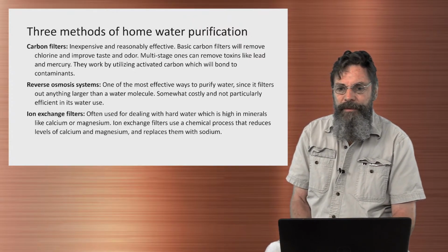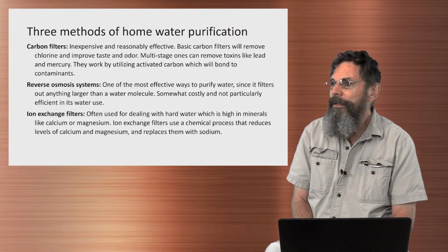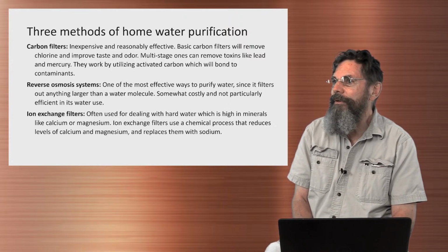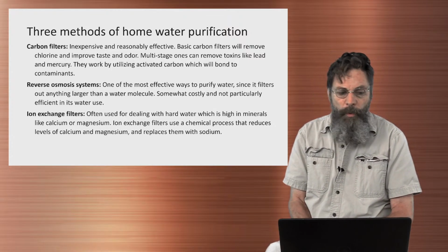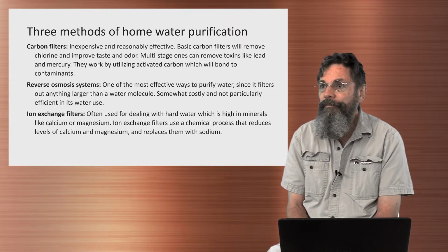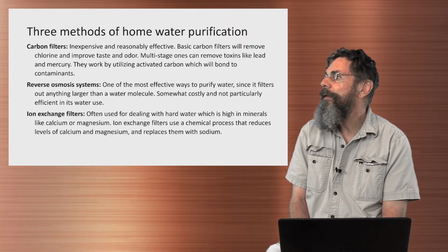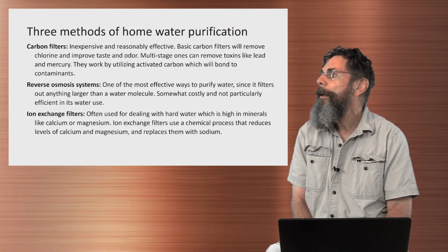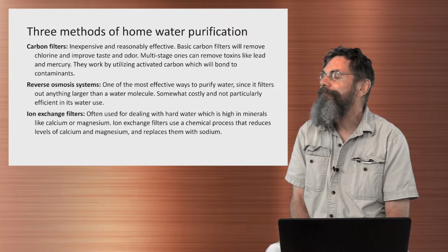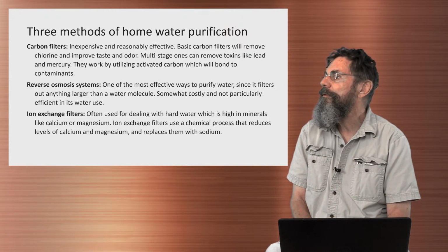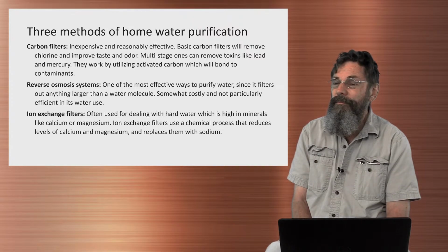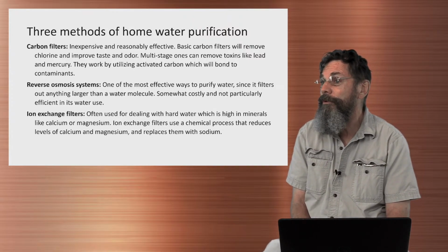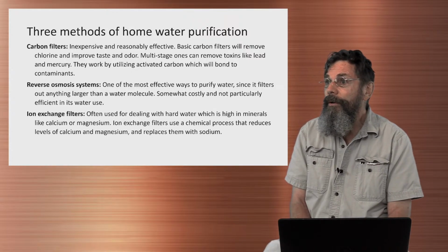Ion exchange filters are used often. I didn't have a picture of one, but they're usually tall, narrow cylinders that have a meter gauge at the top, and they're basically hard water processors that will strip out calcium and magnesium and to some extent iron. It cleanses the water and gives a better sense of taste, and replaces the calcium and magnesium essentially with sodium or salt, which is another thought.